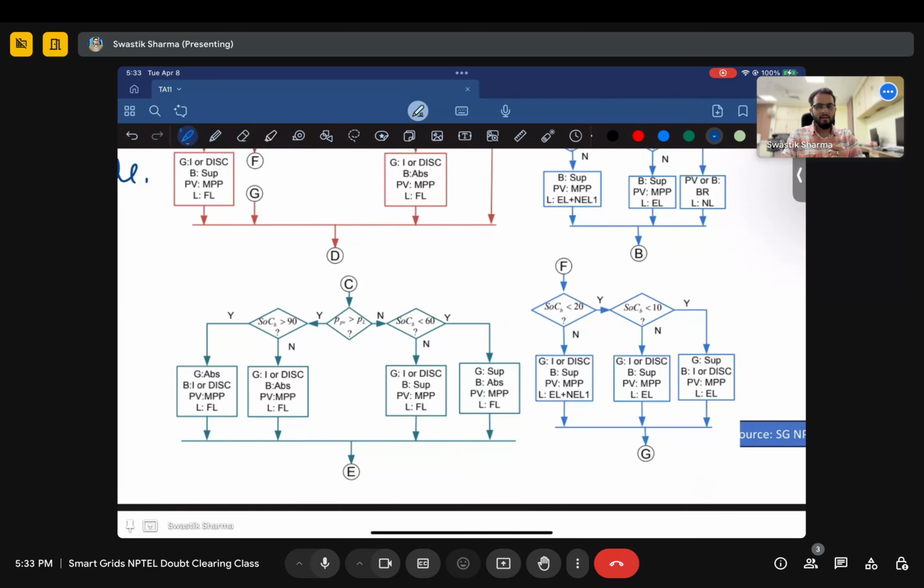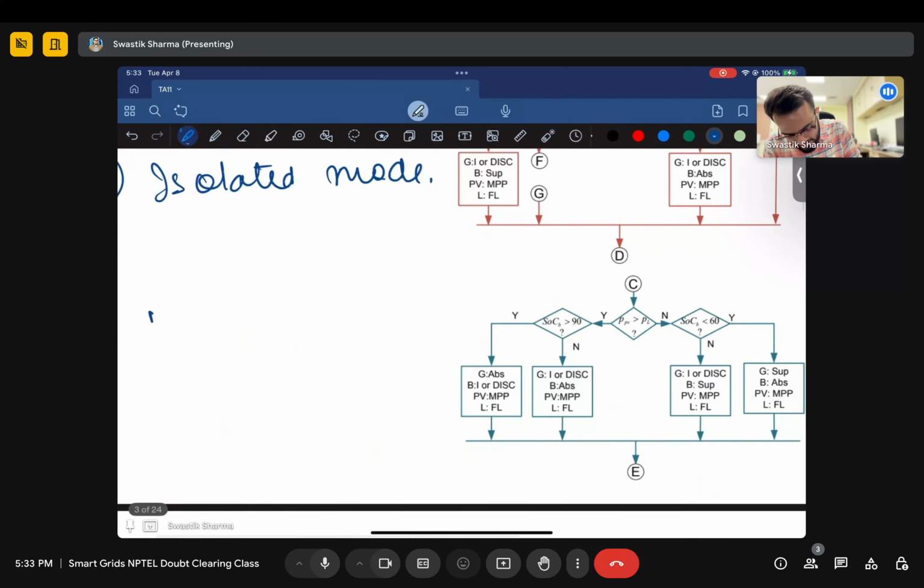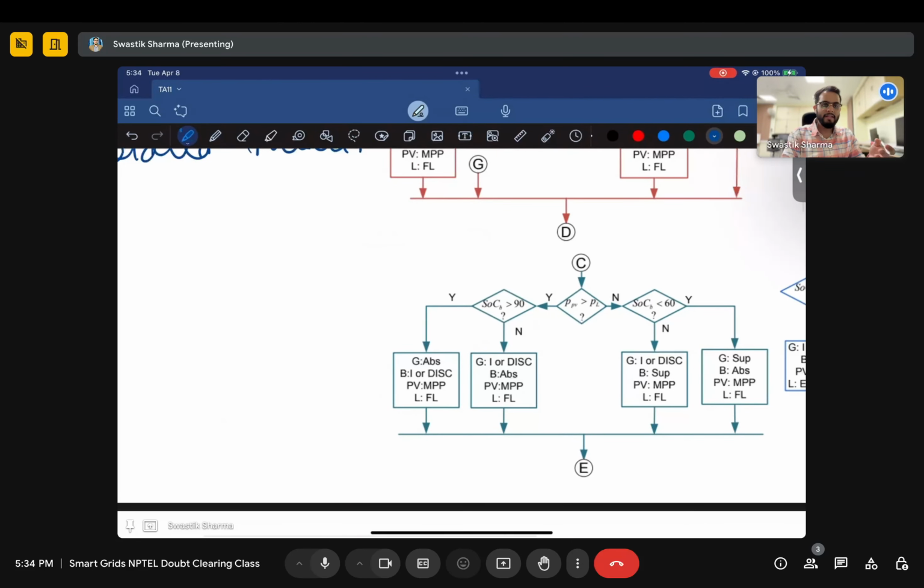I don't know if you have heard, but there are instances in the power markets that there are negative LMPs. What do negative prices mean? Negative prices mean that the grid operator is willing to give you money to increase your load. That's precisely what negative prices mean. That if you are generating, the grid operator wants money from you, if at all you are generating, right? So that is what negative prices essentially are, and it may not so happen that the grid operator would always want you to keep absorbing extra power that you are generating, right?